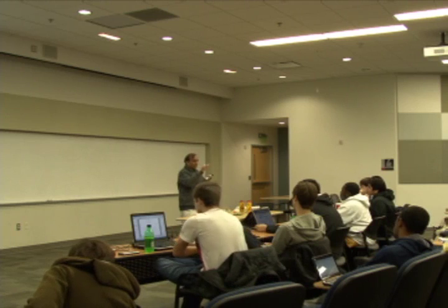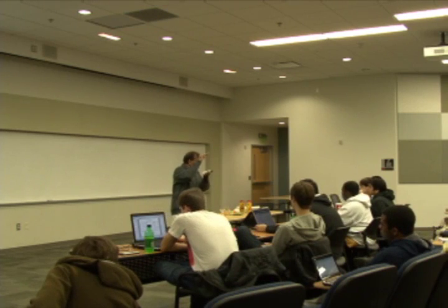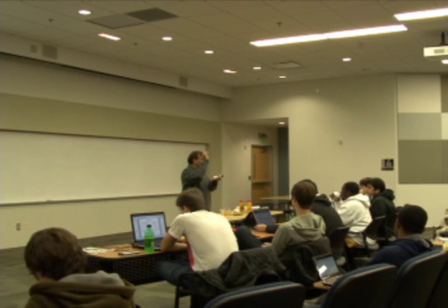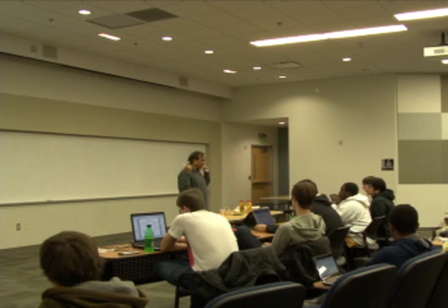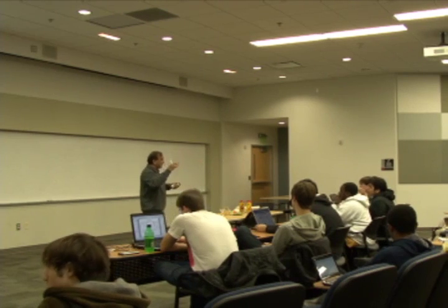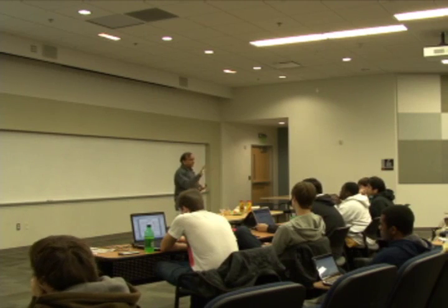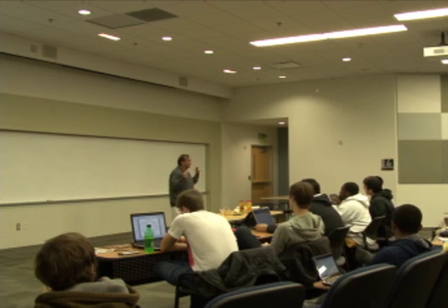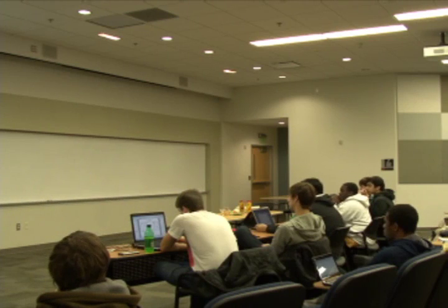You asked an excellent question. That is, we are wasting a significant number of ROM locations for all the times that Z is 1 when we don't need it. Okay, so we'll come back to that in a minute on how we can control that. But is this idea clear, that how we are doing this micro branch? Okay, so now tell me how we can do the decode microstate, macro state.